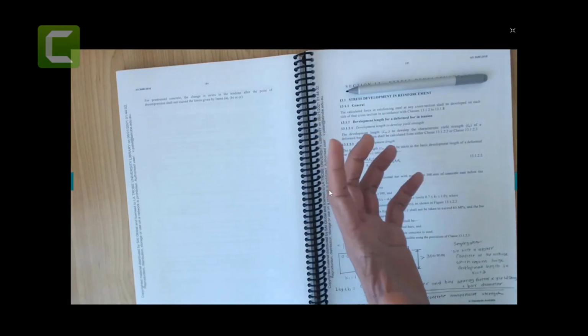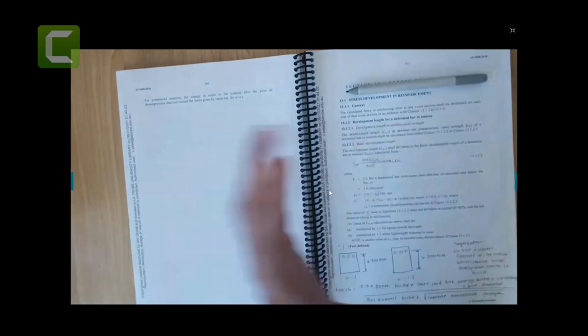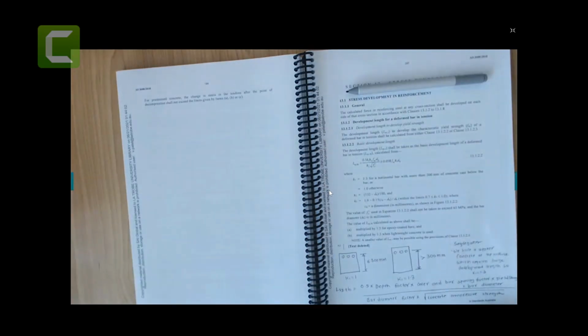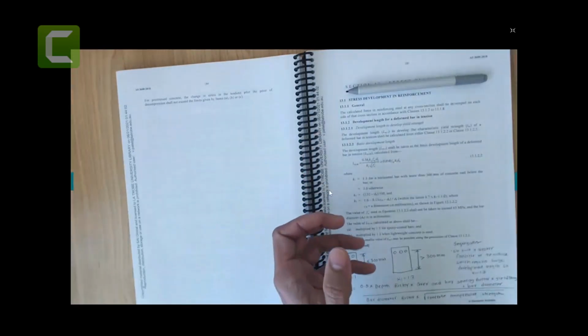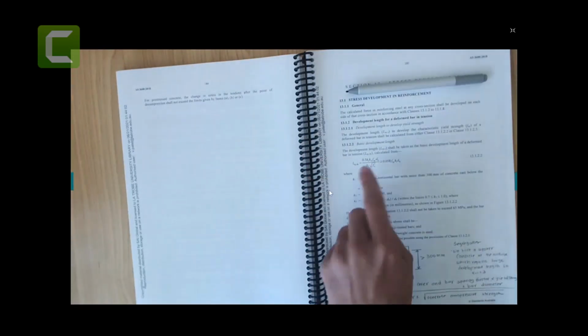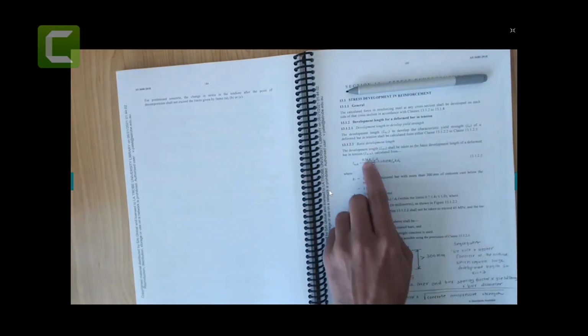Because if you are working on multi-story buildings and you just increase an extra bit of this reinforcement, you are talking about $500,000 extra cost for your steel rebar. So that is significant. You just need to efficiently design your development length. So I hope you understand K1. You don't have much option, 1.3 and 1. Now K2